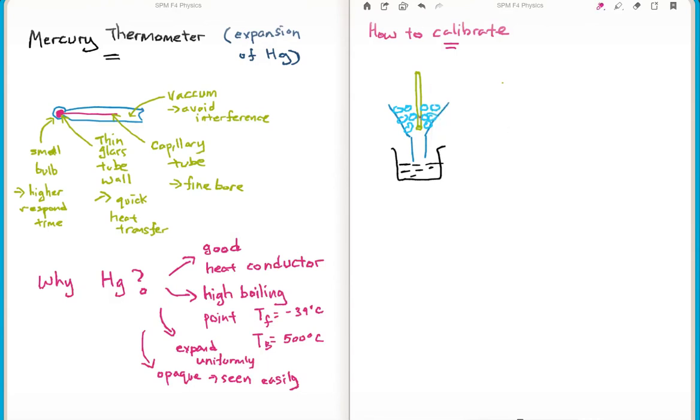So you have this length, isn't it? It goes down to this length, isn't it? After half an hour, you do not expect the heat can be transferred so efficiently the moment you get the reading. No way to do that. Please answer the questions. So do not do it, because heat transfer takes time. So you measure this height in mm perhaps. This is my initial length, L0. And in this case, definitely T is equal to 0 degrees C. Wait for it to stabilize.